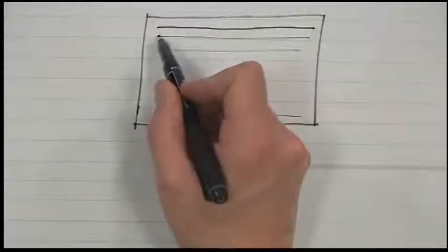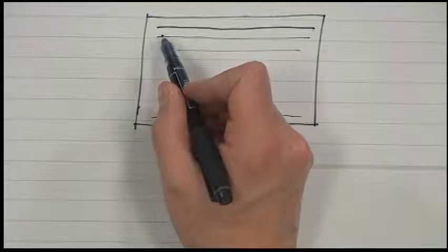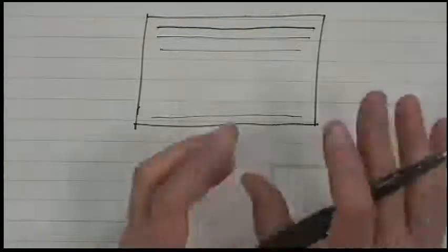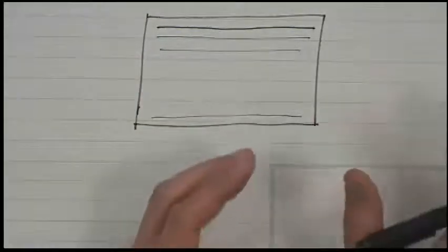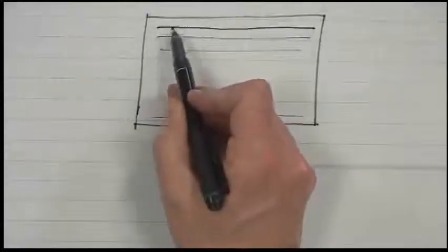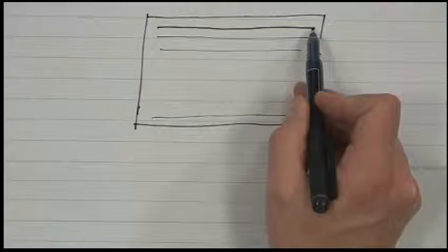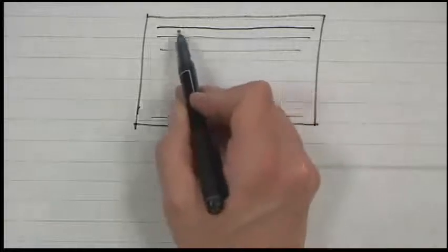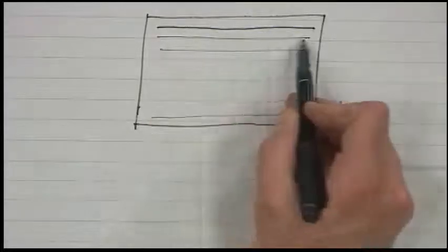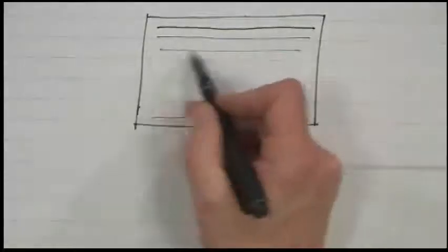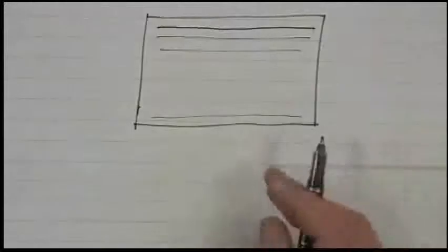The analog signal had to be designed so it could actually work with real analog electronics. It wasn't like today where you just encode everything as compactly as possible, send it over to the computer, and it decodes it. There was no storage. As the video signal goes across the screen, it writes on the screen, and then there has to be a blanking time that gives the electron beam time to come back again. Then it writes across. It writes first the even lines, and then the odd lines. That's the interlaced video.